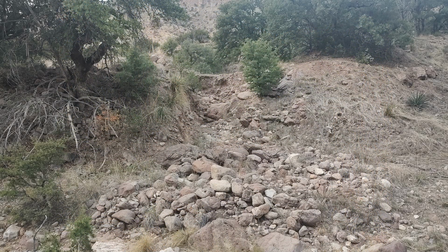The infrequent but torrential rains in the desert sent water rushing down the valley. The runoff quickly filled the pond. The pond then overflowed the dam because the spillway was too narrow and it was too high in elevation.